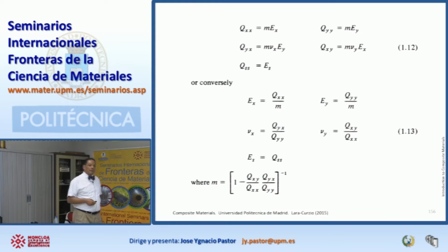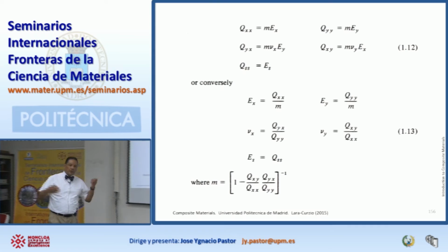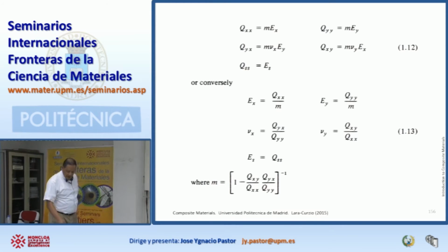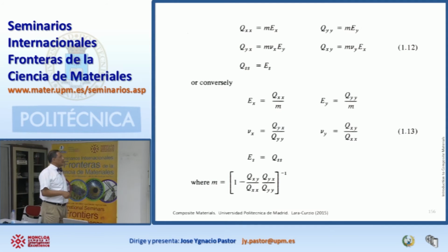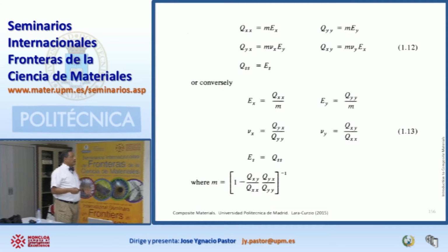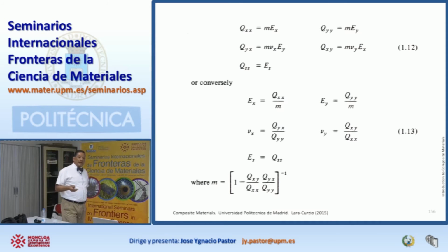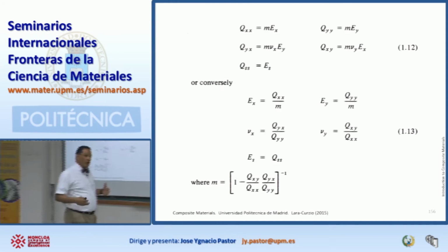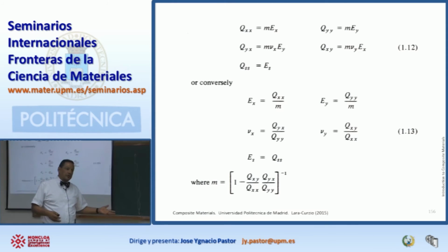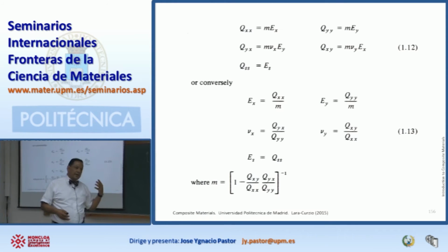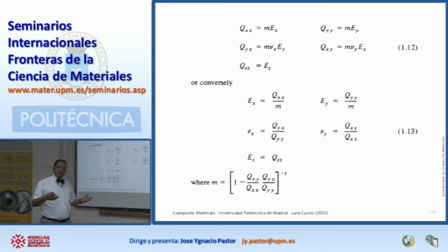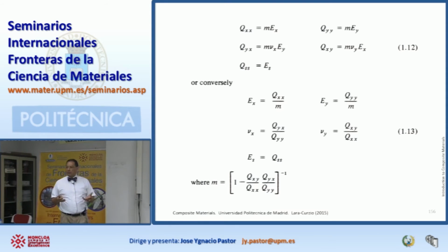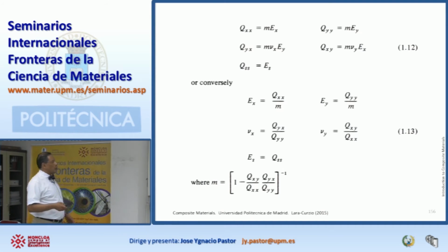And this is very convenient because once you know these values, you can actually read them in a table. You can put them into a matrix, and then you can calculate. Once you know the strains, you can calculate the stresses. If you know the stresses, you can calculate the strains. And this is what design engineers do. I mean, if you have a bridge, and you know the type of loading, you decide what type of material to use based on the stiffness or compliance and vice versa, okay? It really boils down to knowing the stiffness values of the material that you're using to design your structure. And once you know them, that's it.